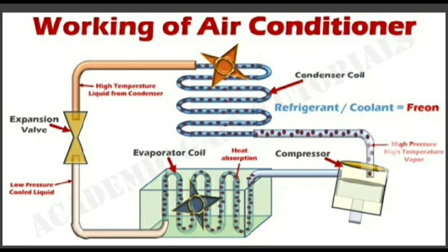We know that compression and expansion are opposites to one another. Here in compression we needed to increase the temperature of the refrigerant, so we increased pressure by compressing the refrigerant Freon and thus increased temperature. So, similarly, now we need to cool down the temperature of the liquid refrigerant coming from the condenser, so we have to cause expansion, which will reduce the pressure between the refrigerant molecules, which will cool it down simultaneously. Now, this is what happens in the expansion valve.